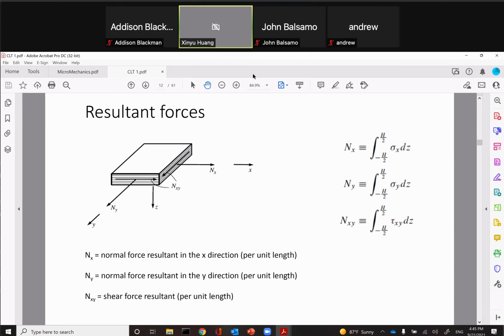So this is not a force. This actually is a linear density of force. You can think of it that way. What this really is, is force per length in this direction. But this one is force per length in this direction. Okay. So you can calculate the total force. Total force will be this linear density multiplied by how long this is. This force will be this linear density multiplied by how long this is.